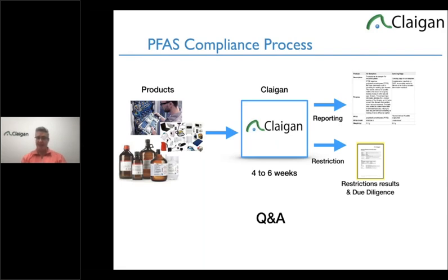So anything that has to really deal with chemical resistance has fluoros everywhere. Wire and cable has a coating, but solid parts, gaskets, tubes, are generally in a chemical resistant situation, and we see them all the time in that situation. Medical devices have it all over the place. They also need the lack of friction of the solid PTFE or FKM or PVDF. It's very advantageous.